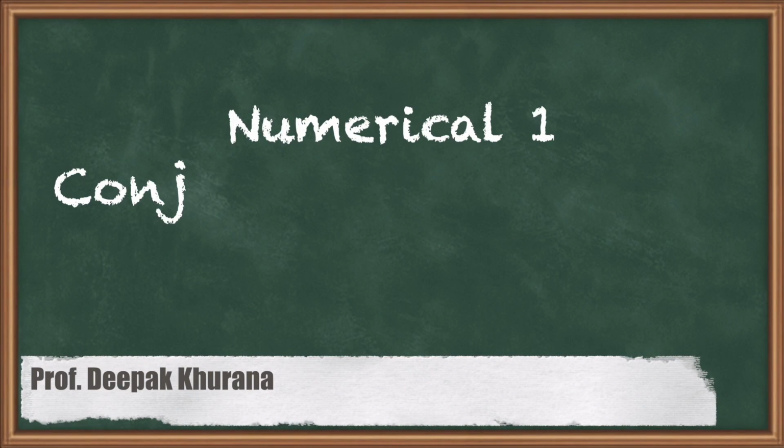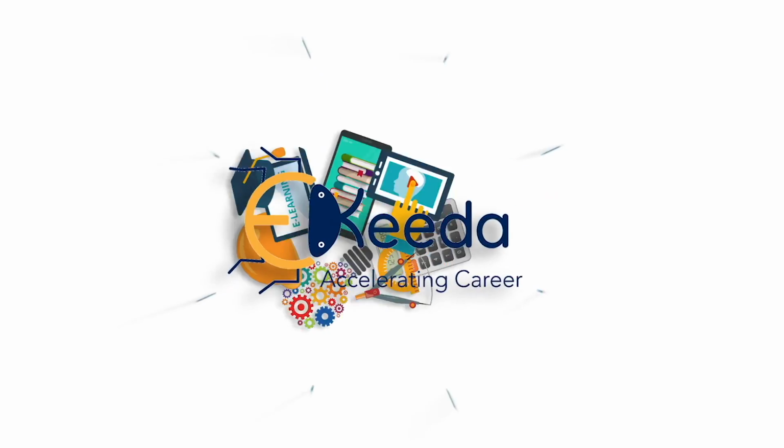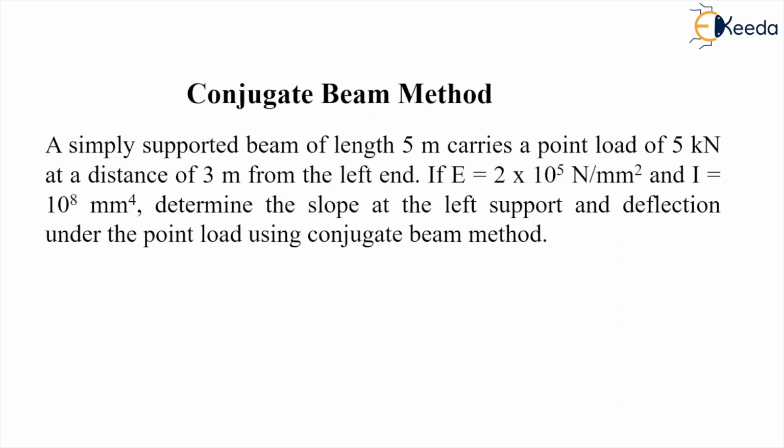Hello dear students, in this session we are going to solve the numerical on conjugate beam method. In this question we are given a simply supported beam of length 5 meter carrying a point load of 5 kilonewton at a distance of 3 meter from the left end. If E is equal to 2 into 10 power 5 Newton per millimeter square and I is 10 to the power 8 millimeter to the power 4, determine the slope at the left support and deflection under the point load